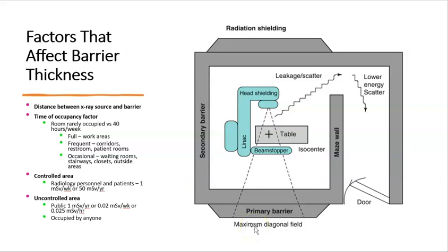So there's a lot of factors that go into this. They say waiting rooms can be occasional. The thing is, we will not put chairs along this wall, or else we would bump up to frequent. We don't want to do that. We want to keep it occasional. And patients are only sitting there, hopefully, for a short period of time. Sometimes we run behind, and the patients will be in there for 2-3 hours. We'd want to move those patients away from this wall, so we just don't even put chairs there. We will here, though. This is an occasional wall.